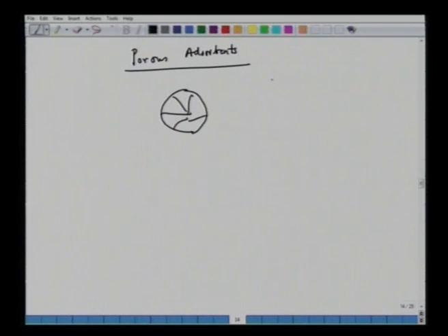We talked of, say, activated charcoals, with very large pores inside. Surface area is some meters square per gram, of the order of even 3000 meters square per gram. Zeolites maybe like 100 meters square per gram. So essentially these are the pores, these are the conduits. So in this case one has to also write down the species balance inside,